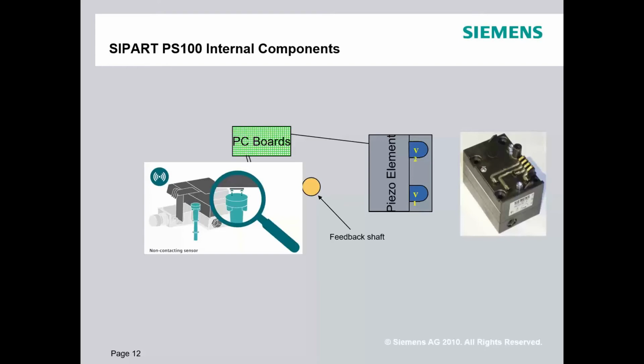It doesn't really matter: butterfly valves, linear valves, ball valves or whatever, I can get you the best bang for your buck. If you're using a valve, what I see every day, because I'm an old valve guy, is that what somebody needed was a really expensive linear valve. What they ended up with, because it was cheaper, was a ball valve or a butterfly valve, which is probably not the world's best control. Now, can I make all your problems go away? Absolutely not. However, with a digital positioner, I can get you the best bang for your buck.